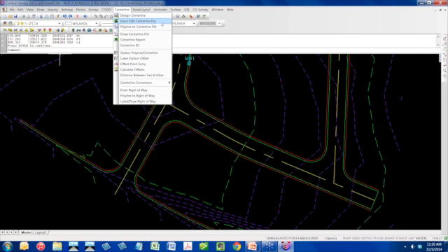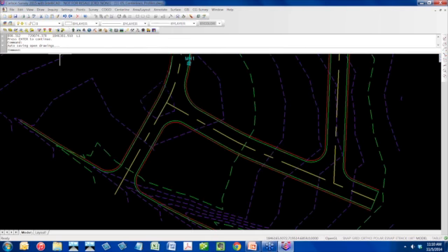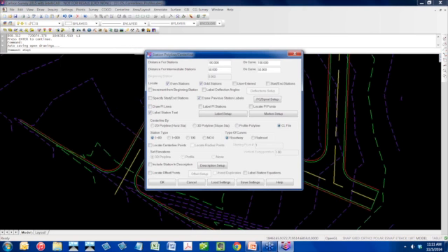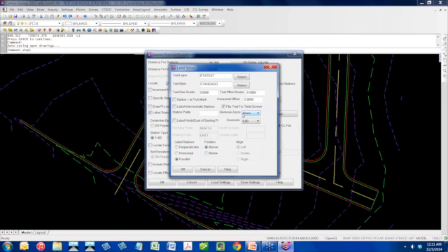Let's go ahead and actually let me station it first. So notice the name of this command, Station Polyline Centerline. And that's important because you don't technically have to create a centerline file in order to put stationing on it. You can actually just station just the polyline in your drawing if you want to. So the distance for stations, distance for intermediate stations, your labeling setup. Now there's thousands of options in here in profiles for labeling and annotation.